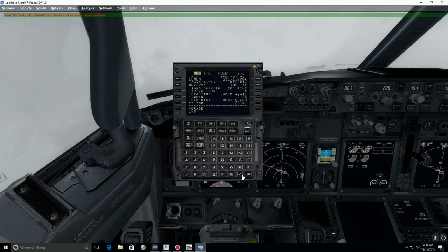so let's change it to left turn. 149 left turn. And that's it. Execute. Another thing we want to do is maybe to reduce a little bit the aircraft weight, as the runway is not very long and we have a steep approach at some point.